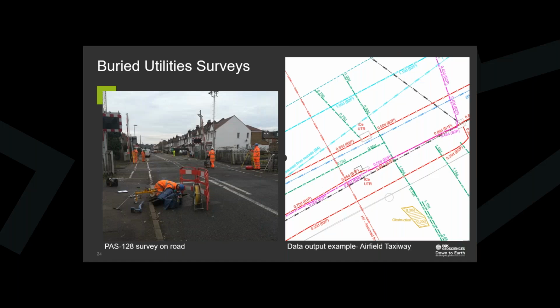And then the last one we're going to look at is the buried utilities survey. These can often be instructed alongside a pavement assessment survey. As you're using GPR, you're using it in different ways, but you can do them together, especially with the use of modern high density towed arrays. Essentially, yes, we can produce a map of the utilities. Generally, it's a lot more involved and more time on site, because it's not just GPR. We'd have to do cover lifting and EML tracing and things like that. But it's something we can do if needed.